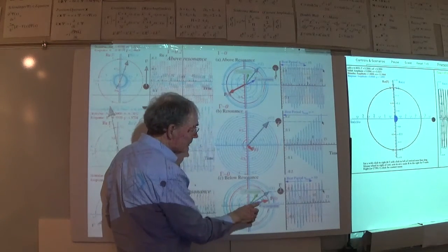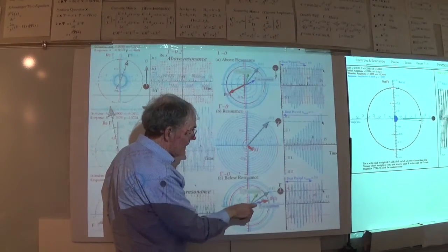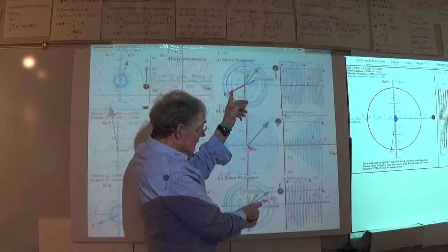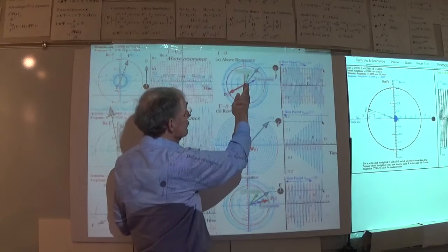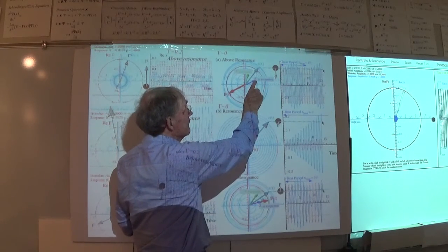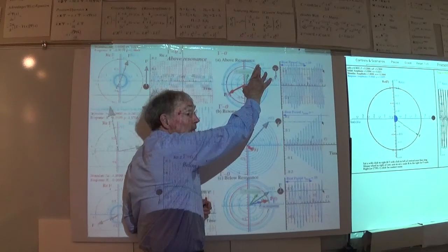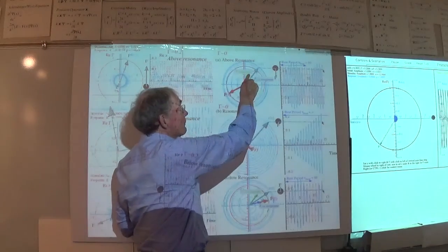Here it's just pretty close to the force. It's sitting right on top of it, in fact. You see, here it's pi out of phase with the response, and it's the sum of those two, the transient behavior plus the steady state response, that gives you where the thing is right at the moment. So the little force triangle here for the resonant plane.